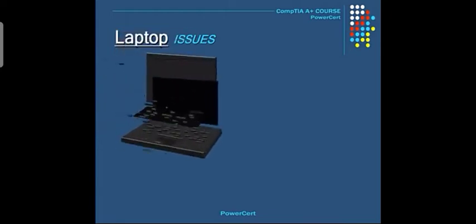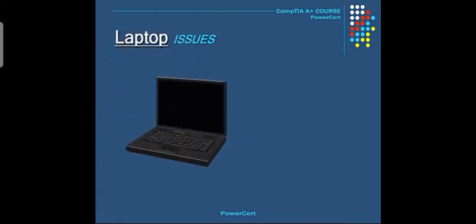Now, as far as troubleshooting issues with laptops, one of the main problems is when you turn the power on, your screen is blank. Nothing shows up on the screen. Now, you may hear the fans running, and you may see the LEDs turn on, but your screen is still blank. And this is called a no display issue.